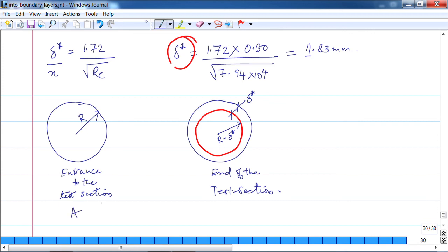This is section A and this is section B. So, VB times area B, where V is velocity, and it's the same fluid so rho is the same and I am cancelling that out, is equal to VA times area A. Basically we need to calculate VB, which is equal to VA times area A by area B.